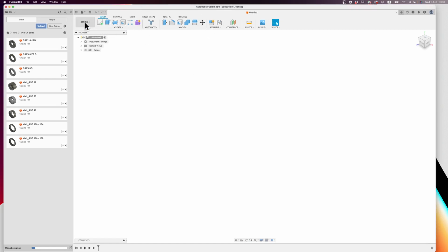In our case, I'm using Autodesk Fusion 360. The assumption here is that you're trying to design a chamber for CF, but KF, or any metal sealed one, would work very similarly. So CF is metal sealed for ultra high vacuum applications. And you're not going to be the one making it, but you're going to send it to a company that will check if all of the wall thicknesses are correct, and if everything can be made.